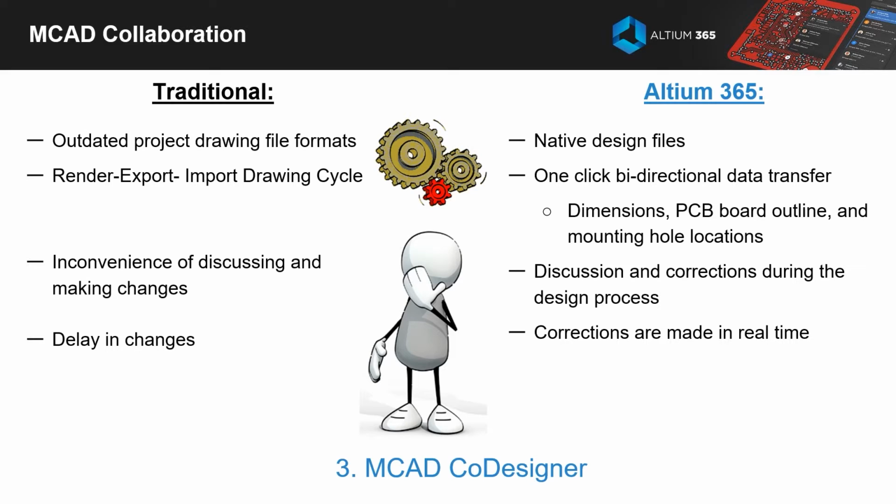You simply push your designs over to the workspace, and then the mechanical team can pull the files into their MCAD tool. Each push gives you the opportunity to comment on changes, improving communication while providing traceability. The design data is automatically translated into native MCAD files so that they can work with the files in the context of the enclosure. In turn, a full model of the circuit board with the location of mounting holes, the necessary connectors, and keep out areas can be sent directly to Altium Designer.